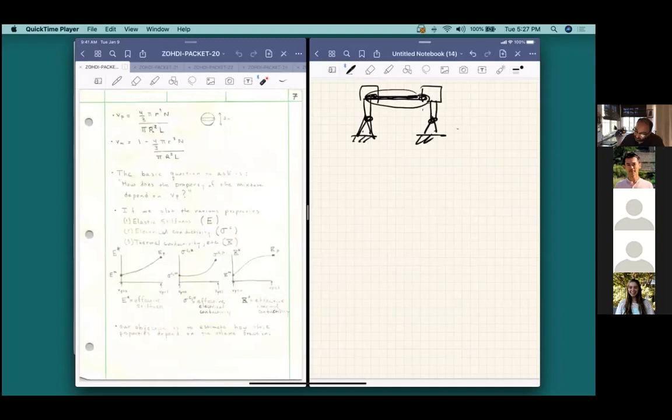First of all, I'd probably want this thing to be pretty stiff because I don't want it to sag. If it were starting to sag, that might be a problem because when the wind starts to become relatively strong, we're going to start to get vibrations. So clearly I want this thing to be relatively taut and stiff. Number two, I'd like it to actually do its job, which is conduct the electricity. So I also want to get the properties of the conductivity.